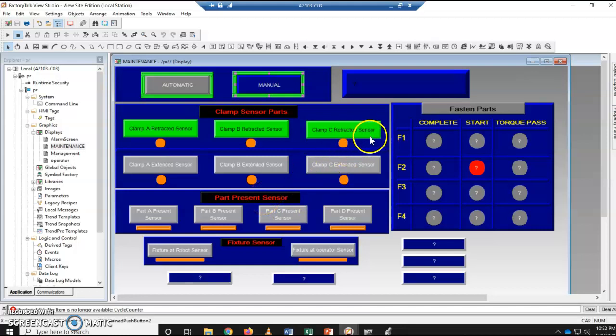So you need to have an indicator, and that indicator should connect to a logic, and that logic should show that there is an error. So it's a separate error for each of them: extend, retract, for clamp A, B, and C. Just indicator? Yeah, just indicator.